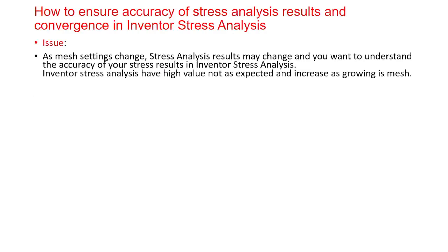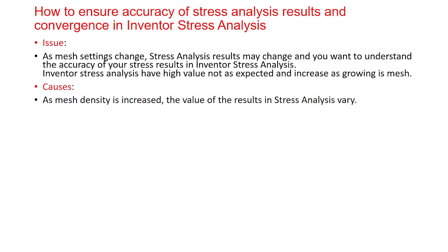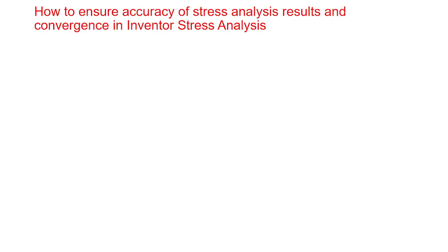The other technique is related with convergence in Inventor stress analysis. It can be seen that if we increase the number of elements, the results of the analysis change, in most cases to a greater stress value.